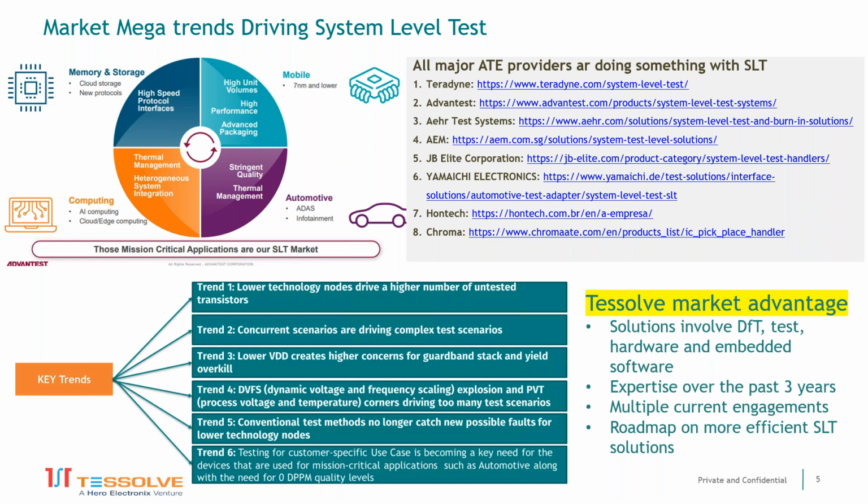The test may run in 5, 6, 10 seconds, and then any chip that fails those tests will be binned, and any passing ones will go off, as they are okay to go to market effectively. But because you're in a mobile environment, for example, trying to get millions of chips a month potentially, you need highly parallel environments with lots of robots doing the work for you.